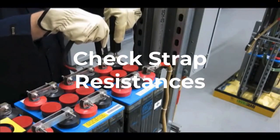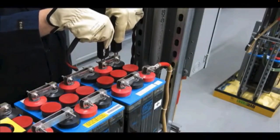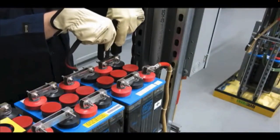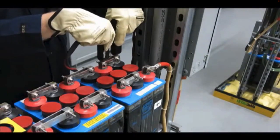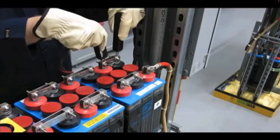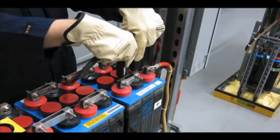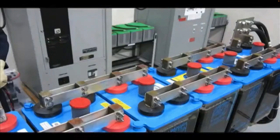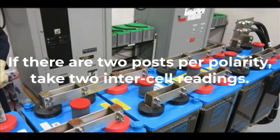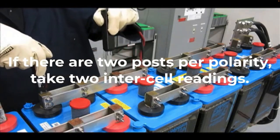Check the strap resistances. Again, you want to make the measurement from post to post so that we can measure the connection of the post to the strap. And then simply continue along the battery string. Now, if there are 2 posts per polarity, take 2 intercell readings.